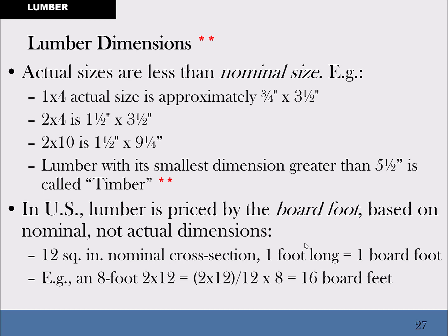But once you get beyond the 2x6, okay, a 2x6 would be 1.5 inches by 5.5 inches. So that's true. But once you get beyond 2x6s, 2x8s, 2x10s, 2x12s, then the 2-inch still stays the same. It's going to be 1.5 inches. But the 8-inch board, the 10-inch board, the 12-inch board, they officially subtract off 3/4 of an inch. And so a 2x8 is considered to be 7.25 inches wide, not 8 inches. So it's 3/4 less.